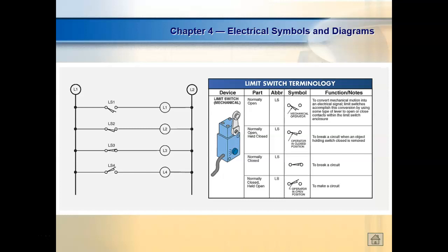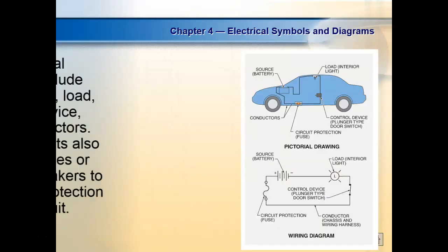Push switches, limit switches, and other switches, we don't have that problem. Which gets confusing because on a single pole, we draw it open, normally open position on the top, right? You understand? On the limit switch, it's drawn according to what gravity's trying to do to it, which confuses some people.